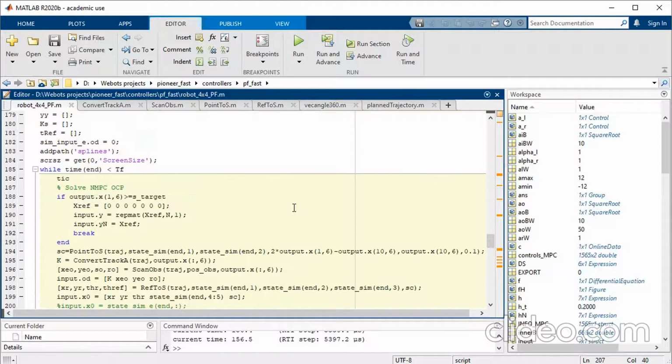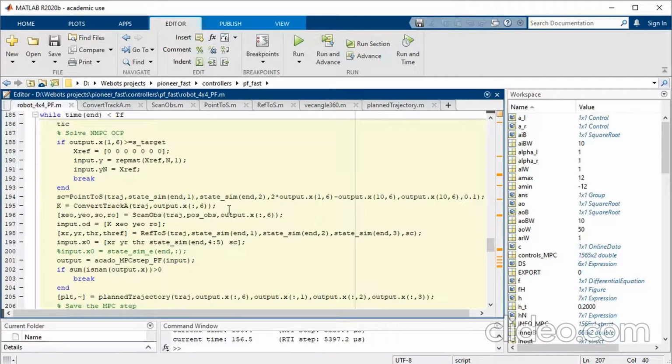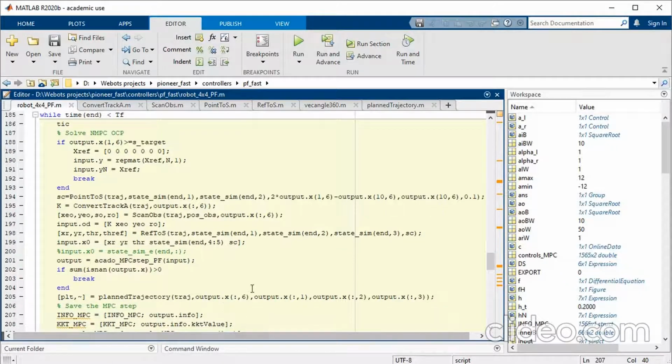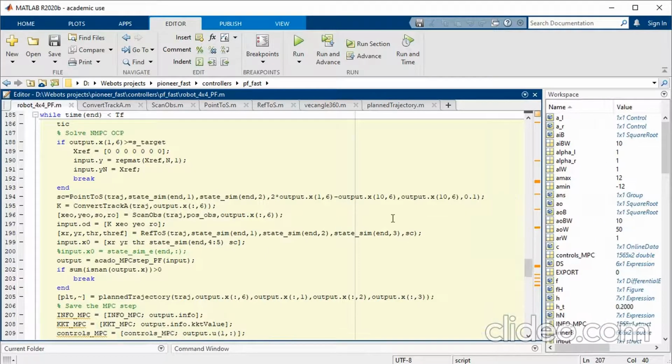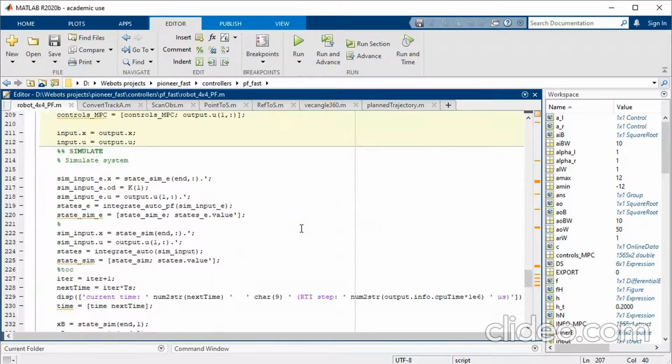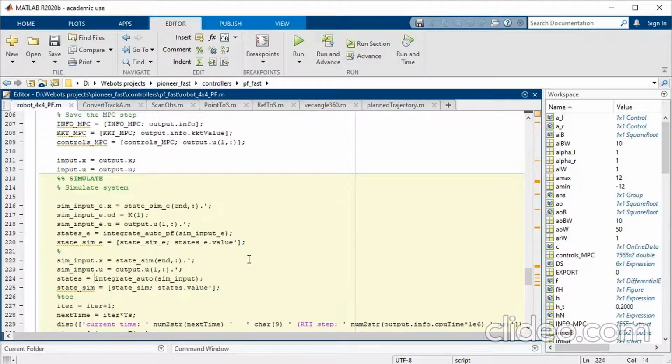So the feedback to the system is also done completely online. It does not take any states from itself. It does this from the simulator, which is this. It gets this state sim, which is a simulator in time, simulates the robot motion in time domain. And the simulator is defined by the model used previously for trajectory tracking model.